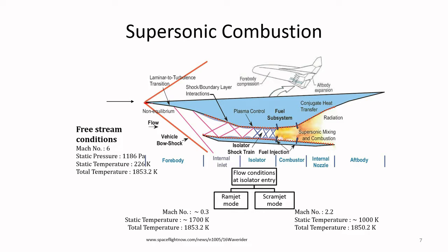Then the flow will flow from a boundary layer along this engine, and there can be a large boundary layer developing, and that boundary layer can transition from laminar to turbulence, and then the boundary layer becomes even thicker. And of course, the larger boundary layer leads to increased drag, which you do not want. So, it might be necessary to bleed off some part of the boundary layer.